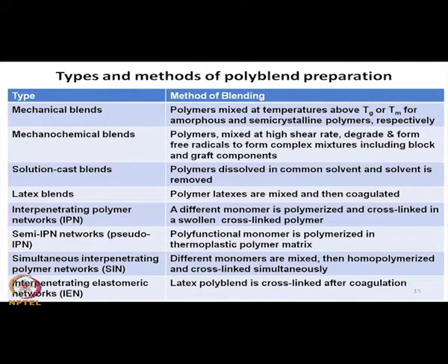After proper selection of proper solvent composition, the component polymers are dissolved in a common solvent and they are mixed, and after mixing the solvent is removed by evaporation, and that can be collected, recovered for reuse, and the product becomes a blend of two component polymers.